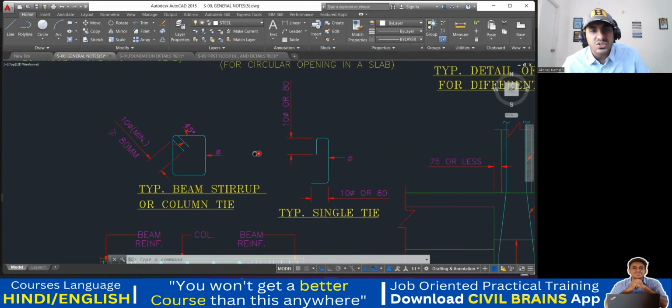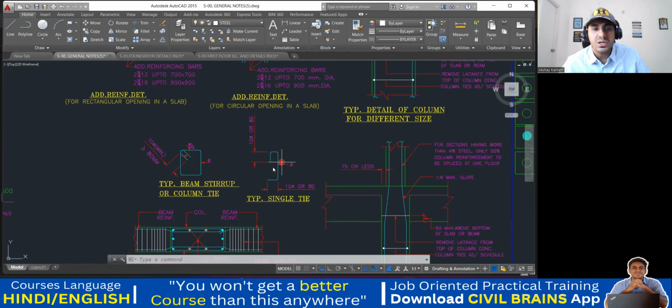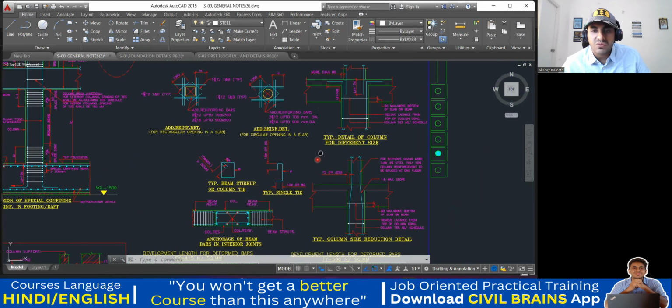Fine. Next, what is it telling us? This is again the same thing, for a 45-degree hook. Sometimes you will provide a hook like this also, like the cross tie in the stirrup we were providing. In the column we were providing something like this. You remember, right? Single tie. So then also you need to do the same thing. This will be 10 times the diameter of the bar or 80 mm. This also will be 10 times the diameter of the bar or 80 mm. You need to follow this. It's written TYP, which stands for typical, beam stirrup or column tie. One and the same.